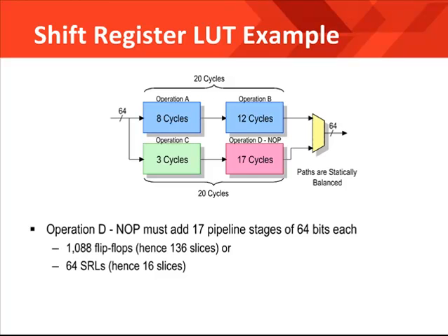Because there are so many registers in the FPGA, pipelining is an effective way of designing to increase design performance. But pipelines can sometimes become unbalanced when too much logic must be generated. It is necessary to delay some of the signals. One of the best uses of the SRL is to add delay to balance pipelines.